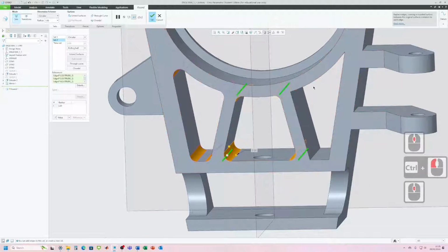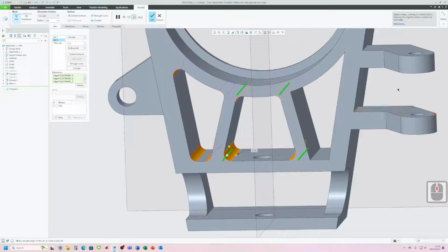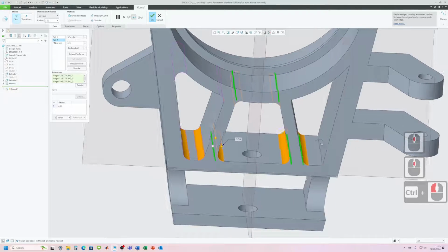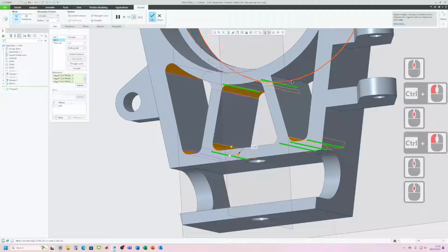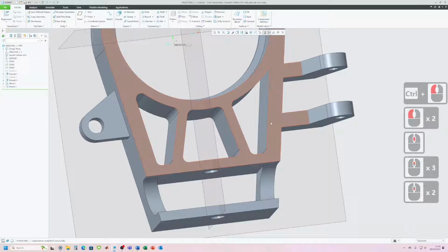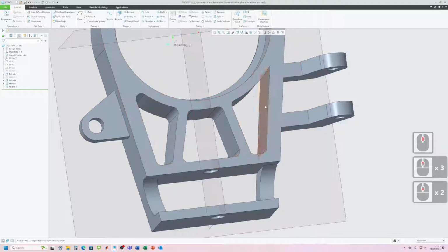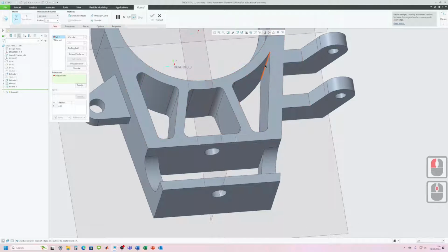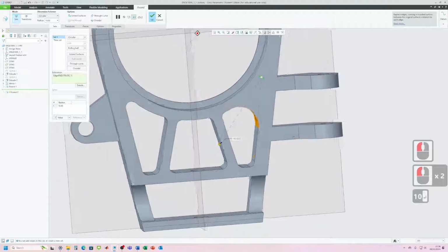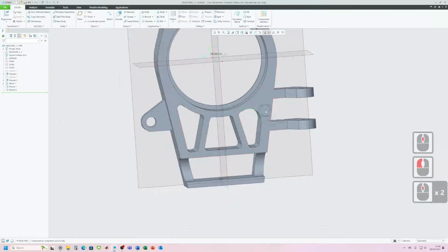Okay, I'm a little bit concerned with this region just because there's quite a lot of force that comes through the steering arm, so I'm a little bit worried about the strengthening here. So what I might do is I'll use rounding here, here, and here. Okay, so that's fine. But I might use a larger round in this section so that I add a bit more material so that the forces are transmitted through it. So let's just add a second round here. How big can we make this? Okay, yeah, so something like that, maybe 10. Hopefully that will help us out a little bit. Okay.